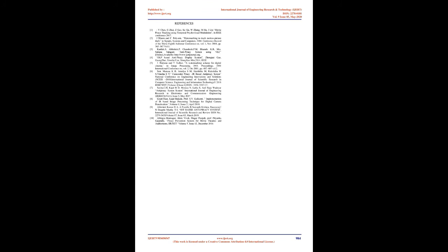The advantage here is that IR rays are in the wavelength range of 700 nm to 1 mm, which is beyond the spectrum of visible light, hence these rays are invisible to the human eyes. But a camcorder can perceive these rays, and this results in distortion of the image. An additional password-based authentication unit is also present for the operator to actuate the IR LEDs.